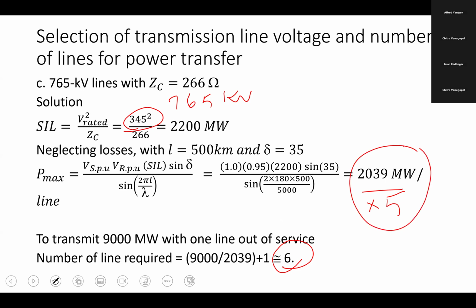So only that much power it can transport. There are some loads which are not getting enough power, right? So those loads will be transferred to another line, another set of lines. That will add as loading to that line, and then it will start to ask for more power because the load is increased on that line. It will ask for more current and more power, which will ask for more reactive power.